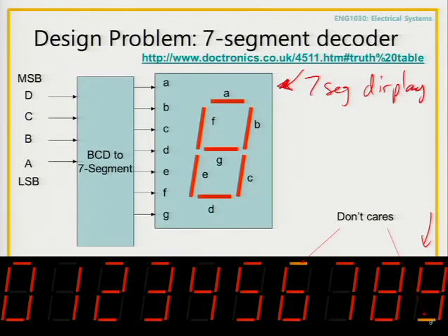And just for fun, there's a couple of segments for certain numbers that we can say we don't care about. For example, on the number 6, if segment A doesn't light up, we don't care, because you could still see that the number 6 is what's meant to be put out on this 7-segment display. Similarly for 9, you could still see what's on the display even if segment D, this lower segment here, doesn't light up. So just for fun, we can say that those are don't cares.